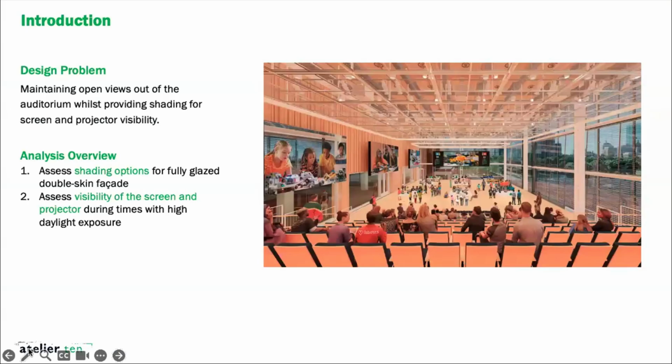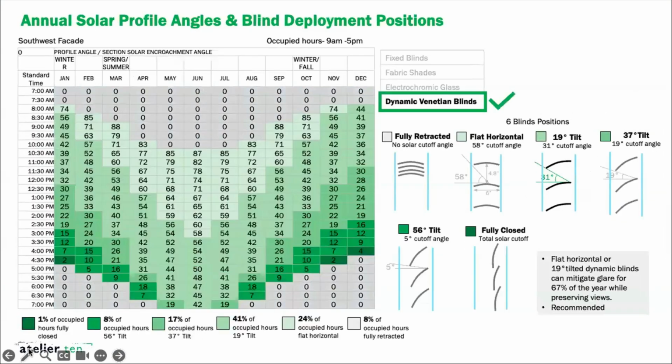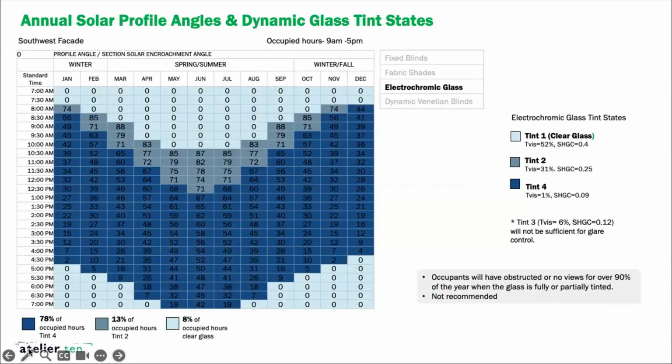Yeah, so you're talking about this project, right? The electrochromic. Okay. Yeah, so this was dependent on the depth of sun penetration, right? Once the sun penetration was going deeper into the space, you would go with the highest tint level. If it was not that deep, then it would go to the lower tint level, etc. I think we forget which product we used as a reference, but we used the product as a reference for when these tint states are activated, depending on the amount of light coming in.